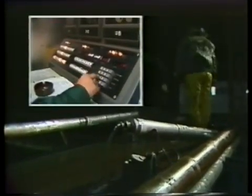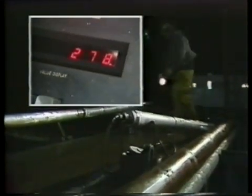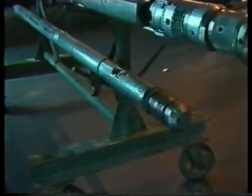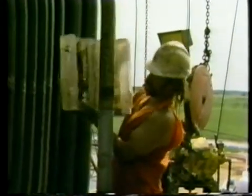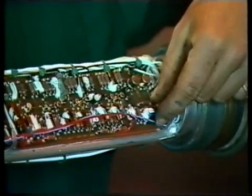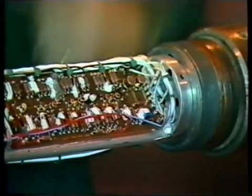This confirms that any changes in tool responses from the shop calibrations are within allowable limits or can be explained. For example, nuclear devices like this neutron density tool are tested with and without the calibration jigs designed to produce a predetermined tool response. Still other devices use built-in calibration tests, like the internal resistors in this resistivity tool.